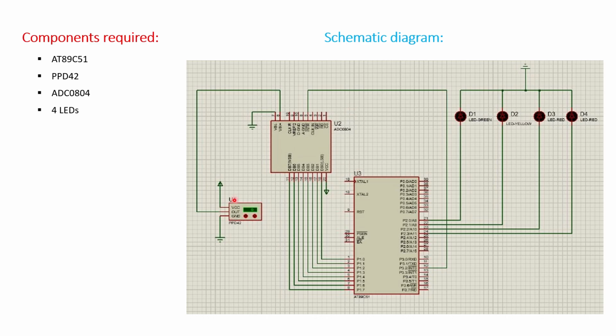Here, firstly, the dust sensor detects the dust particles present in the air. How it detects: it contains an IR light and a photodiode. When the dust particles enter the chamber, they scatter the IR light. This scattered light is detected by the photodiode. The amount of scattered light corresponds to the dust concentration. The sensor provides an analog voltage output that increases with the dust density.